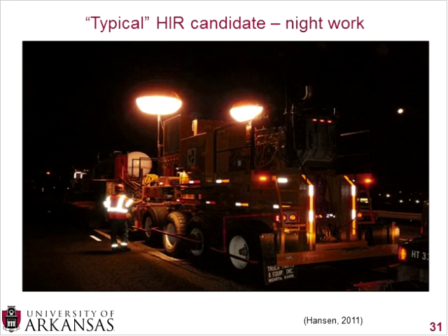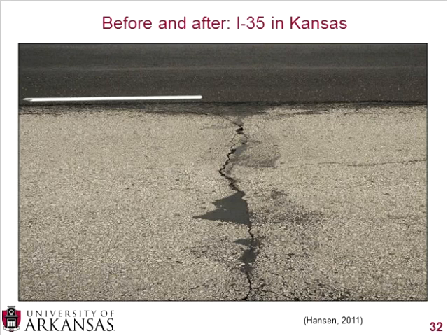Now, I put this one on not because we can look at the roadway and see what kind of existing distresses are on there, but I did just want to point out that HIR can be done during the night. Now, you want to be a little more careful with the pavement temperatures, because obviously you don't have the sun coming down on the pavement. Usually temperatures are a little cooler at night, but if properly managed, you can do HIR at night. So if you're looking at your higher volume roads, this is something that might be of interest, especially on interstates or in urban areas. You can go ahead and try using HIR on those.